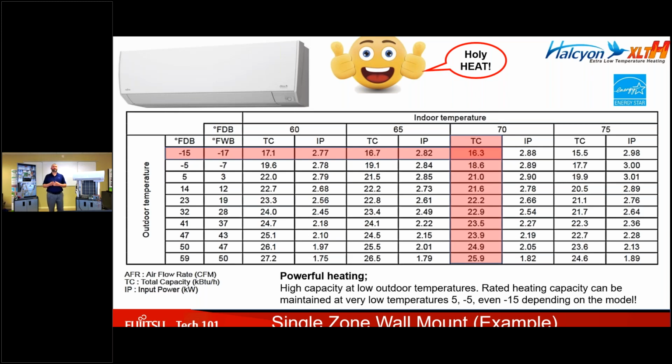Another thing I want everybody to take into consideration is the footprint that we are located. Most of us are going to be from the New York, New Jersey area. Long Island, we may see a little bit lower temperatures when we start to get to upstate New York, but as far as central New Jersey, northern New Jersey, Manhattan, Long Island and such, we're really going to be operating right around the 14-degree design temperature day.